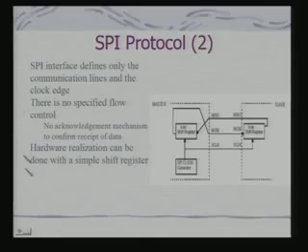So, in that context, the basic hardware realization can be done with a simple shift register. Because shift register, why? Because it is a serial input output. So, if you look in here, you have got the SPI clock generator, and this SPI clock generator would come from the master always, because master is driving the bus. Master would need to know that for a particular slave, what kind of clock configuration is defined by those 2 parameters that I had earlier discussed.